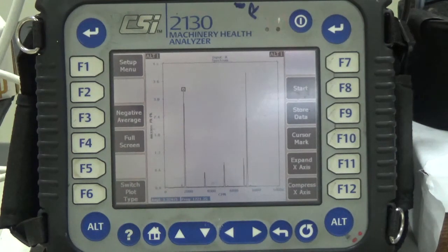Now in this case, when the frequency is equal to RPM, it is telling you that the problem is unbalance, and the amplitude at this frequency, which is 1721, is telling you how much is the unbalance. So the amplitude at this frequency is telling you the amount of unbalance. Now let us see what the other frequencies are here and what they are telling you.